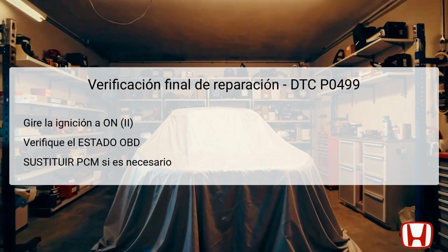For final repair verification, after troubleshooting DTC P0499, begin by turning the ignition switch to the on position once again. This allows you to check the OBD status using the HDS for any lingering issues. If the system indicates a passed condition, troubleshooting is officially complete. And if a PCM was substituted, replace it with the original unit.